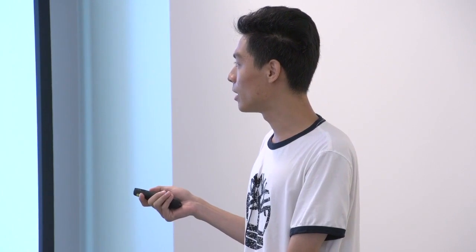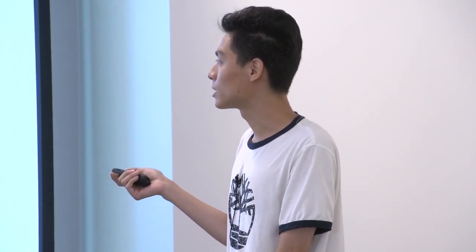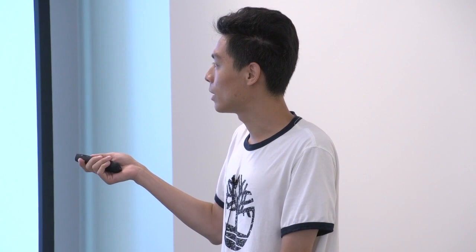Do you expect it to go like that, or do you expect it to plummet even lower as it goes? So this is also based on a previous model that models the retention trend, essentially. It says that after the linear logarithmic transformation of the raw bit error rate and retention time, they should follow a similar linear trend. And it turns out that this trend applies very well for 3D NAND as well.